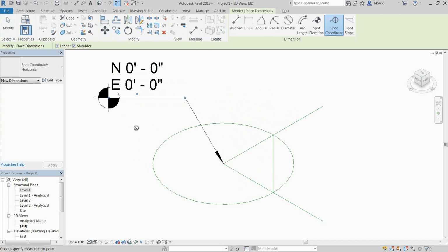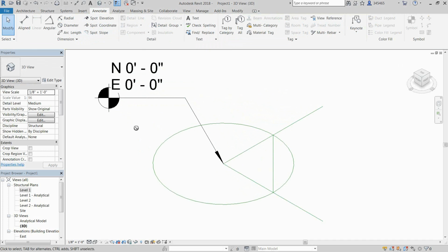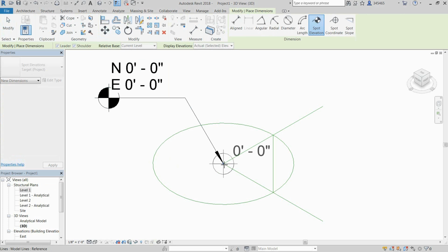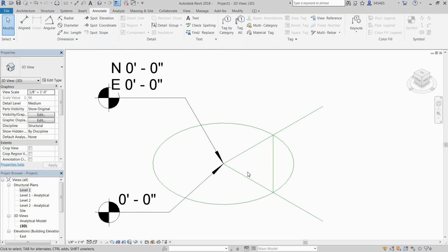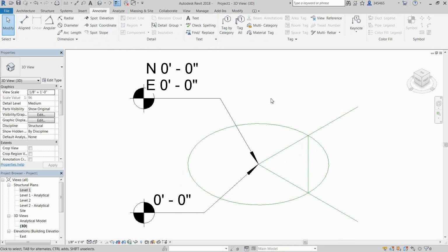And again, I will put in another point in the project origin. The reason we switched to level 1 when we began is also so that the elevation would be at elevation 0, 0. So what we have defined is, in the X, Y, and Z directions, the origin of the Revit model. From this point we will then begin showing how we might set up grid lines and a grid system in Revit, and some common practices when coordinating with teams in Revit and Advanced Steel.